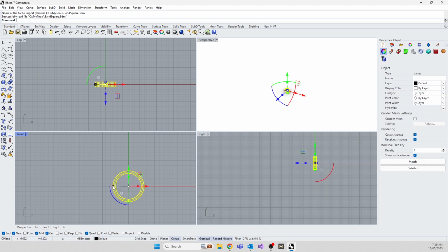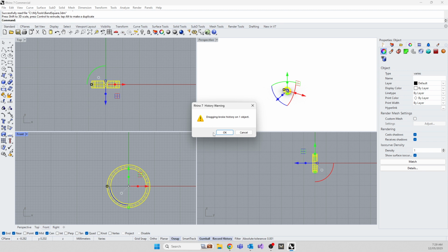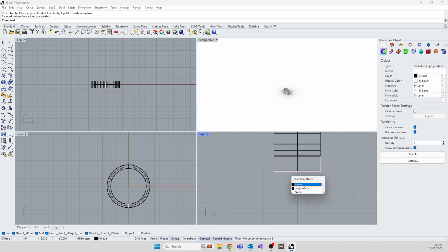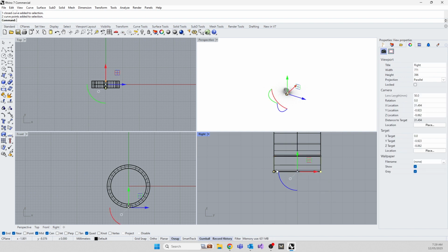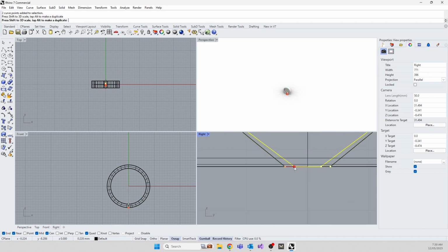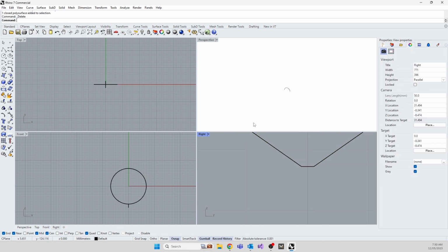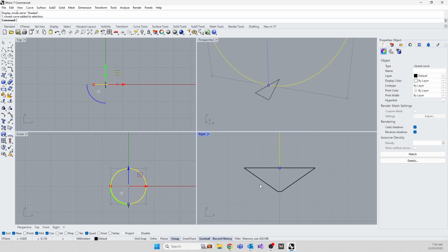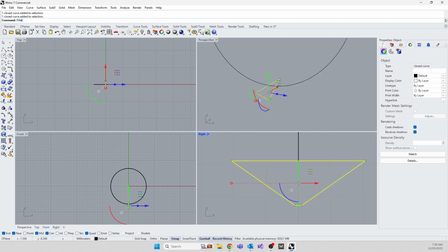I'm going to scale it up to 16.8, which generally speaking is, grab those two guys, I'm going to scale them together. Oops, no, don't be like that. Okay, let's delete this guy. And the similar thing you can do now, so let's fix this. Let's fillet the corners, 0.2. All right, that's better. And let's scale the whole thing in a bit like that.